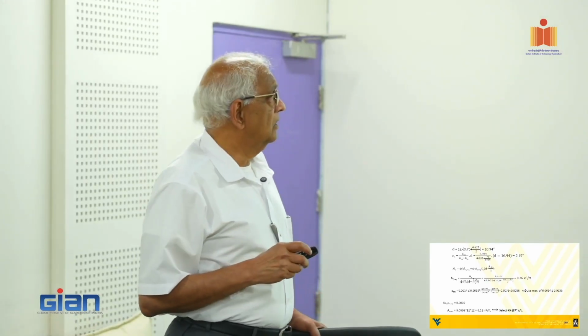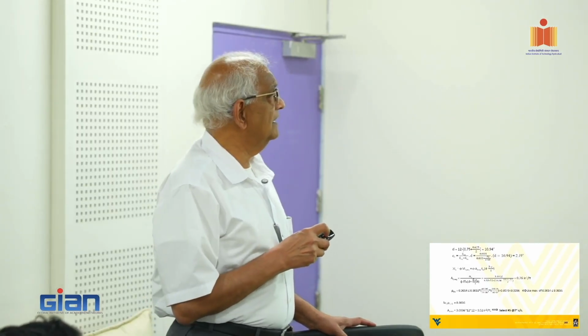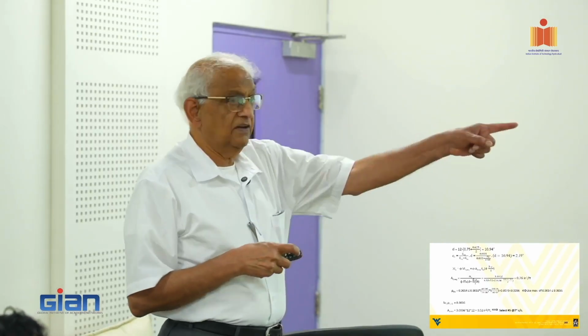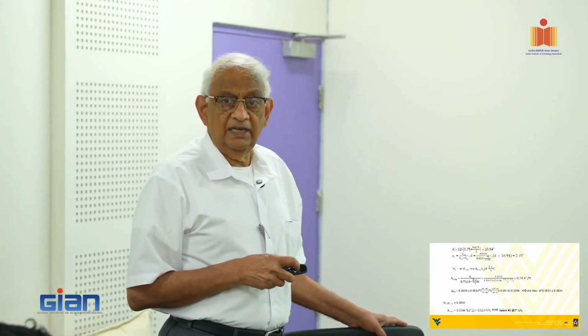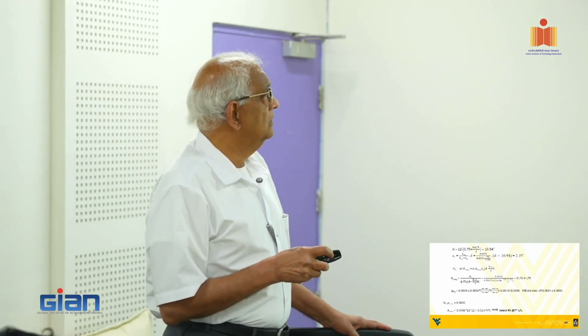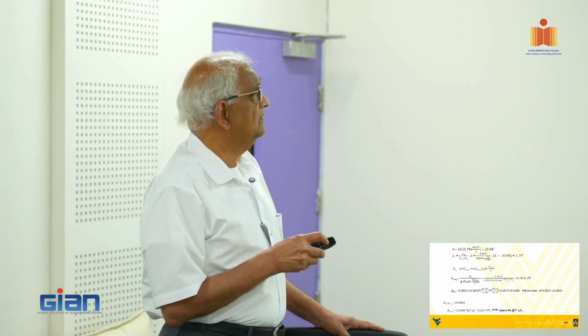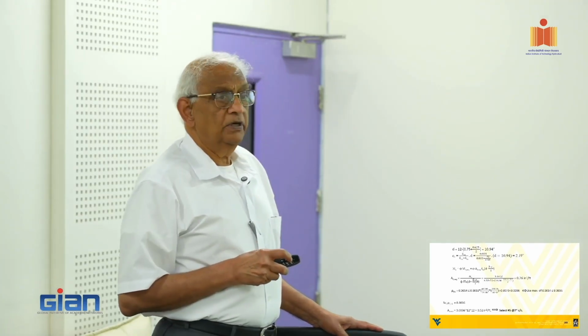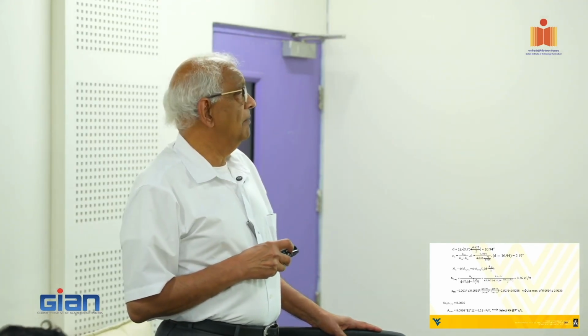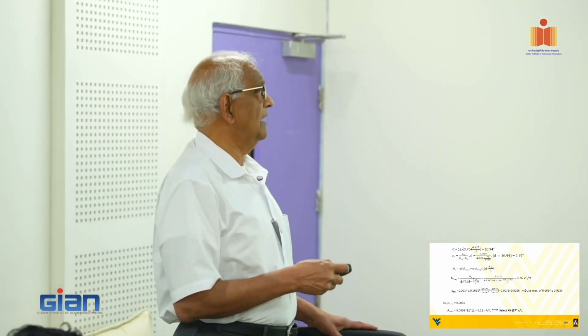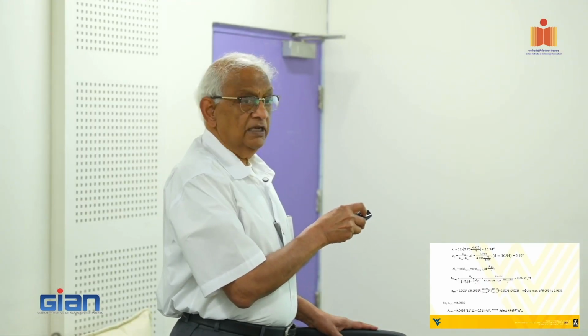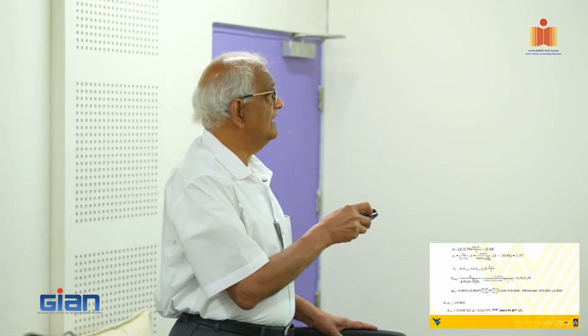Okay. So again, from the strain compatibility, that equation coming straight from that one on that green board. The C value is 2.2 inches, and M being a tension control, that's what we are talking about. Again, the phi factor, please note here, M sub U is phi times M sub N. Exactly.